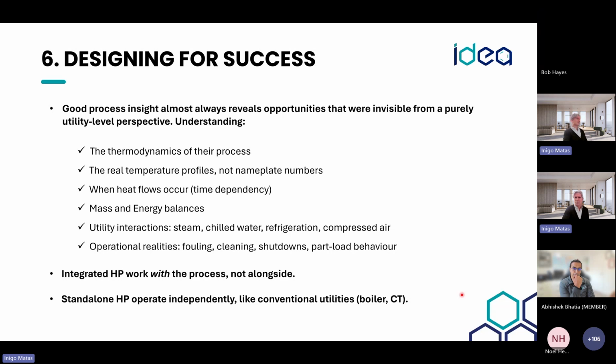As a reminder, integrated heat pumps work with the process, not alongside it, as we can say of the boilers. And that will not be the same case for the standalone heat pump that I was referring to, which operates with air or water, that can operate completely independently and doesn't need the integration.